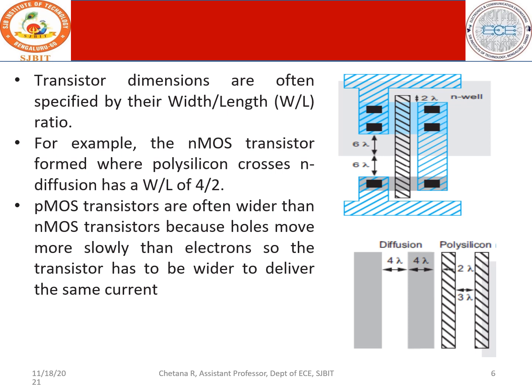Similarly, whatever is indicated in blue color is your metal line, what is indicated in black is your polysilicon line, and this gray shaded region is your N-well. Transistor dimensions are often measured by the W by L ratio, where W indicates the width and L indicates the length. We have W by L as 4 by 2, therefore it has a feature size ratio of 2 to 1.